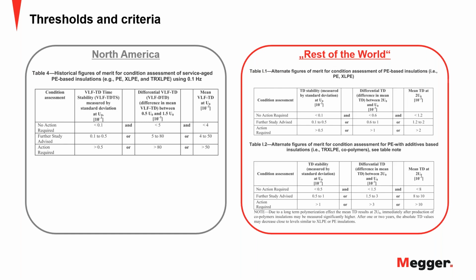Since you have no aging in new cable circuits, it really doesn't give you any information by running a tan delta test. Actually, it could be misleading you to some extent, because of an effect on any new cables. When you make a cable, and most cables today are triple extruded cables, they use certain chemicals to help the extrusion process.